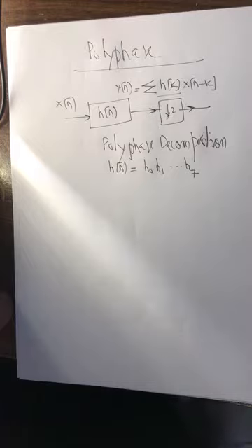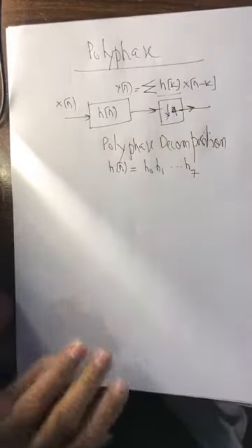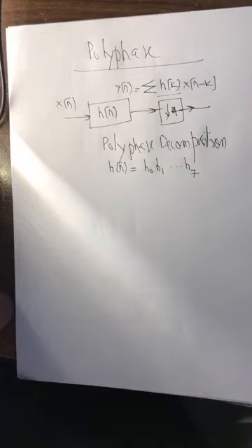Okay, a factor of 4 means that you will keep 1 and throw away 3 samples. Another way of looking at it is that you give it 4 samples and it returns you 1 sample. So this is decimation. Out of every 4 you get 1.